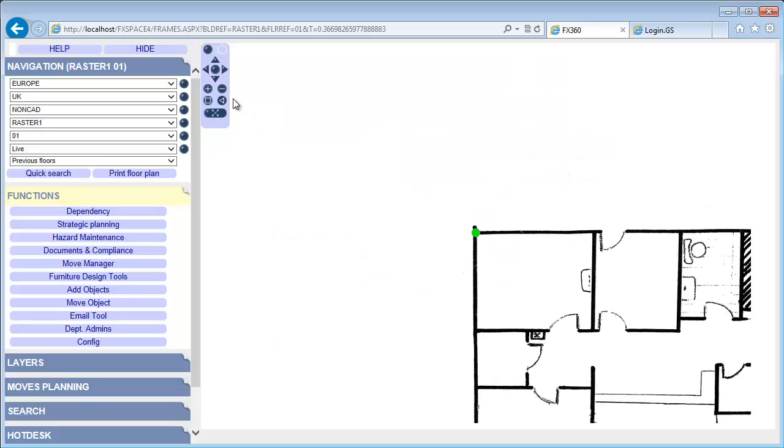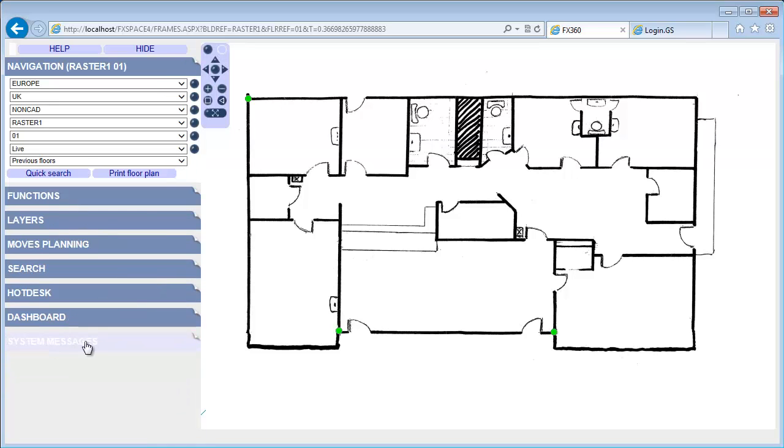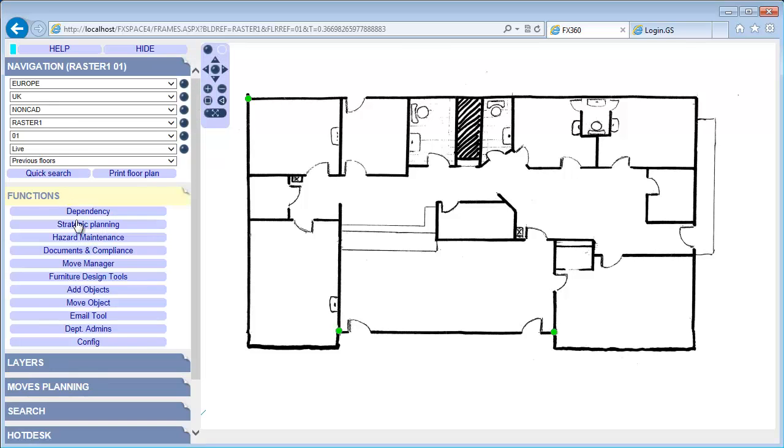Okay, now that's kind of zoomed off the screen, that doesn't matter, we'll just zoom back. Now it appears not to have made any change, but if I select an area, you can see that it's measuring that area based on the coordinates and the distance I put in. So this is now actually scaled, and I can continue here.